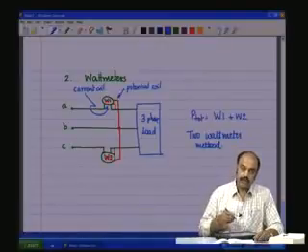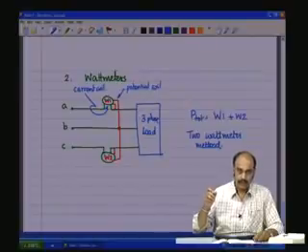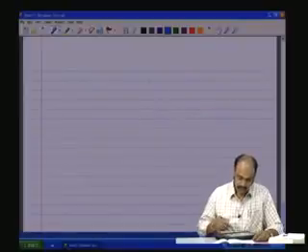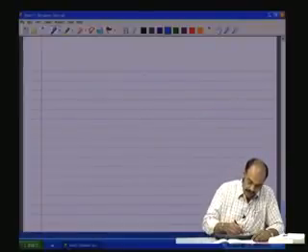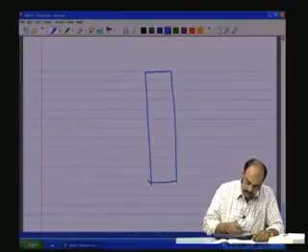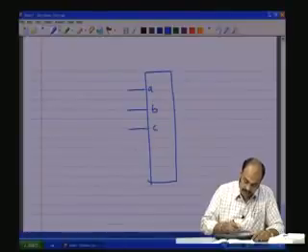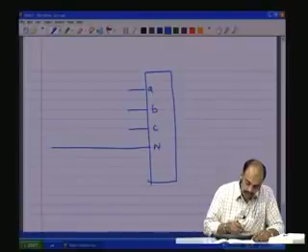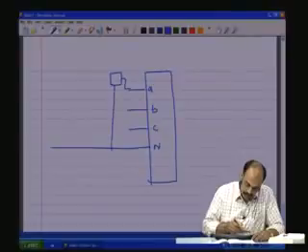In the case of 3-phase circuits where the neutral is also available, meaning 3-phase 4-wire systems, that is, a load with A, B, C and neutral, then with respect to the neutral we have wattmeters connected to each phase.